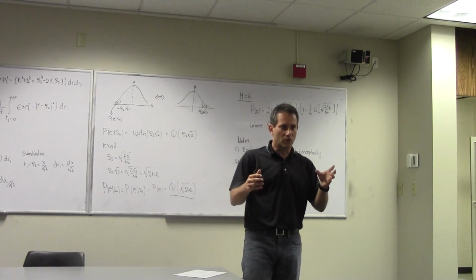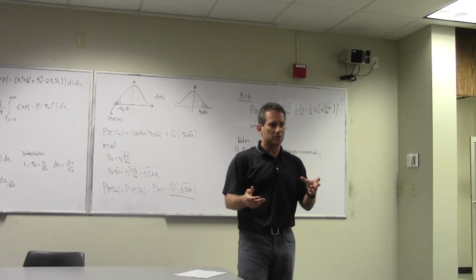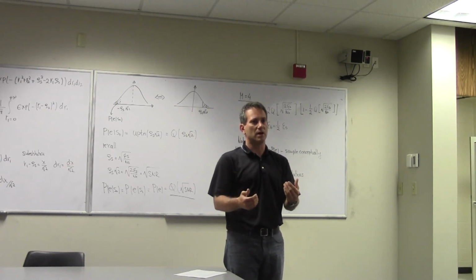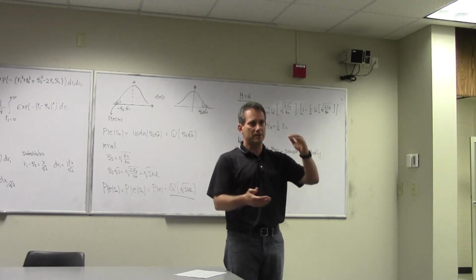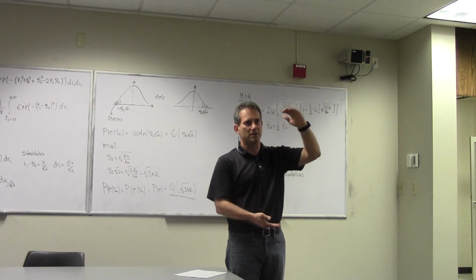But then as I move closer to the source of transmission, my link budget improves, right? My received power goes higher. And the system is smart enough to say, oh, I have plenty of margin to now switch from BPSK to QPSK, and give my user twice the throughput.